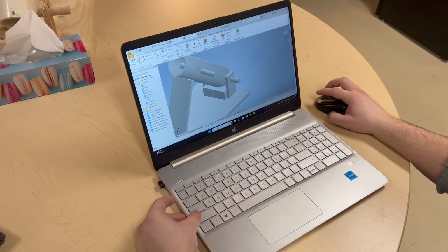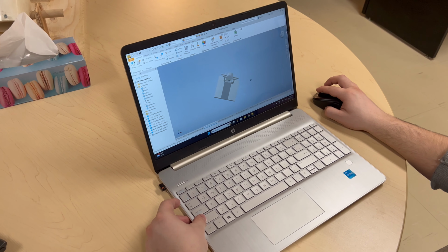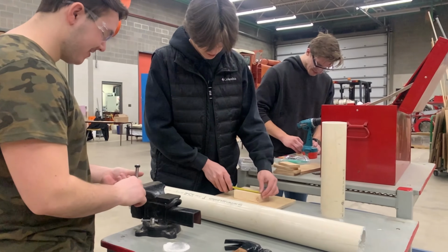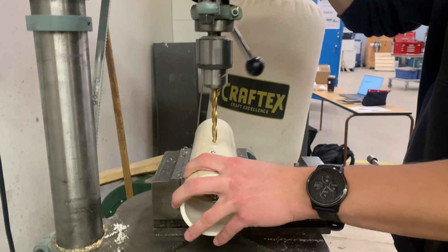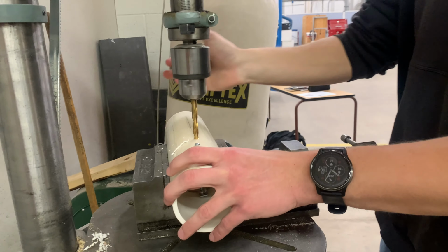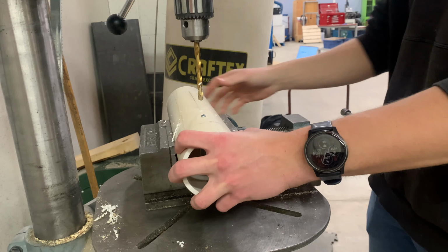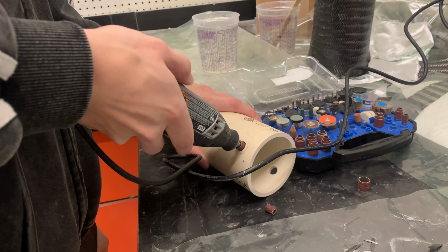With our final design set in play, we began our construction of the spring launcher using the majority of the Fab Lab materials. For our base plate, supports, and height adjuster, we used a 1/4-inch Baltic birch plywood. A 3-inch diameter PVC pipe was without any question our best option, as it gave us enough space to be able to enclose the egg and still limit any energy loss due to its smooth surface.